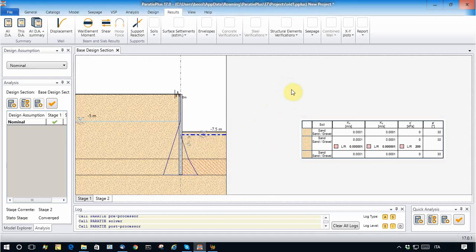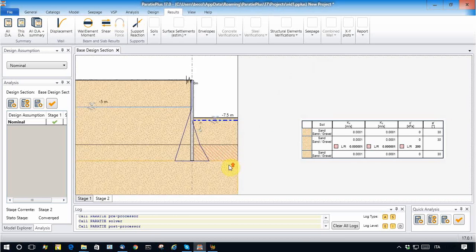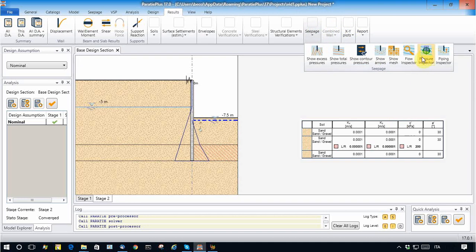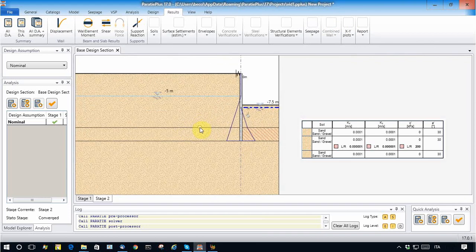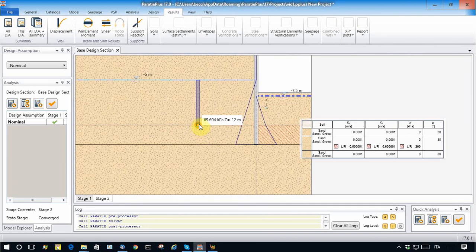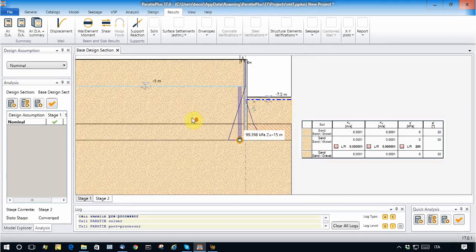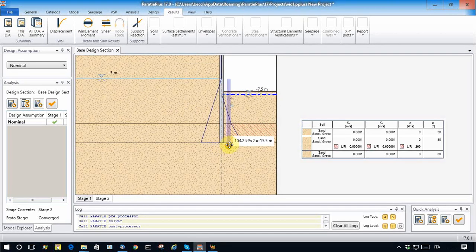Now, what is important is that we can also see which is the water pressure along the model by using another tool that we call the pressure inspector. Pressure inspector is simply a point where you can move around along the model and see how much the pressure is. You see that here the pressure out of the plug essentially has the hydraulic head that reaches the water table in the surrounding soil, and this is also what happens just below the soil plug.